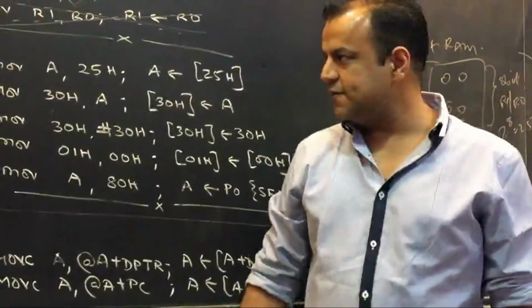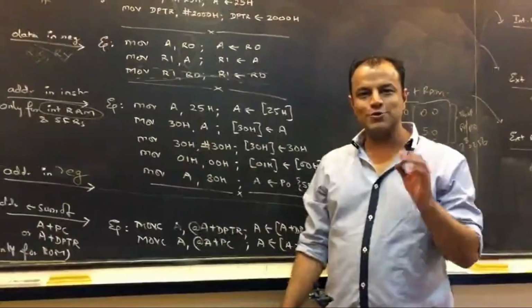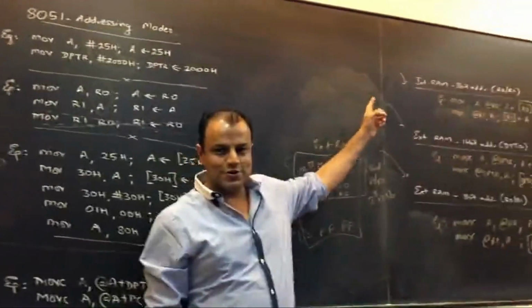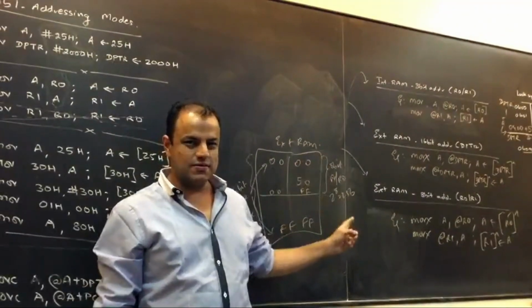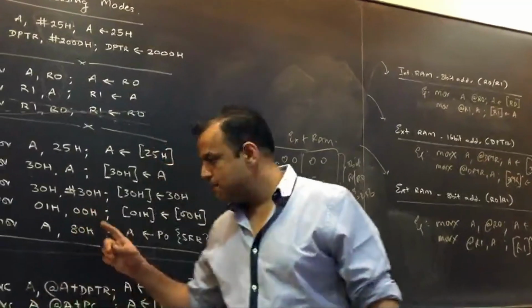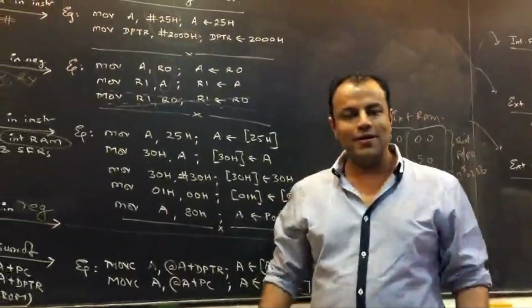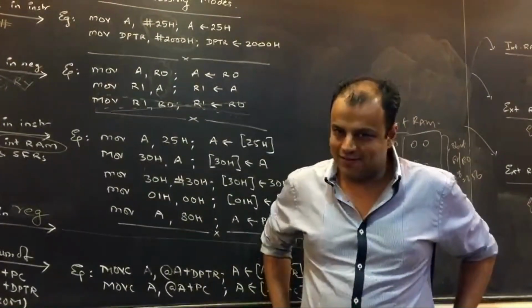Another thing to understand is, MOV works on internal RAM. MOVX works on external RAM. MOVC works on ROM. Now which ROM does it work on? Internal ROM or external ROM?